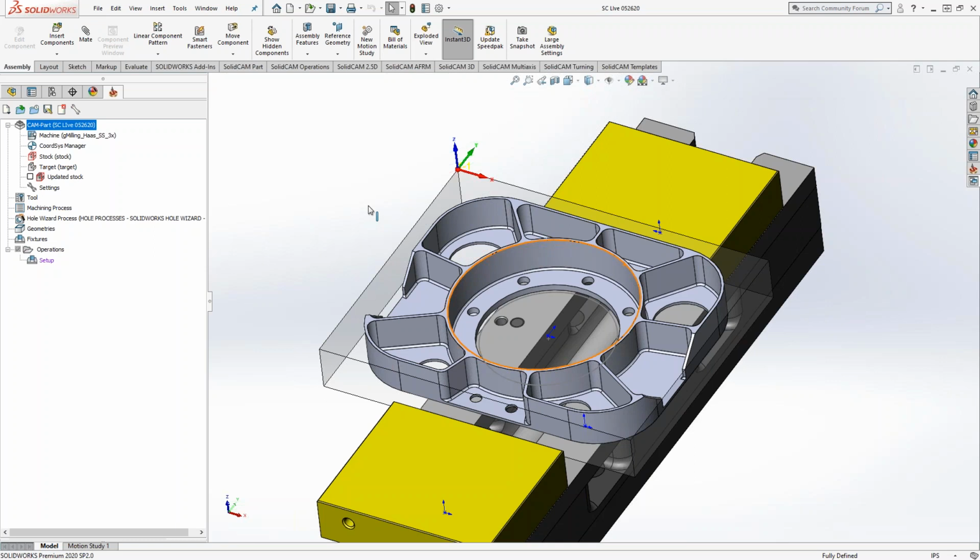And then in your 3D machining, you can put a floor offset. It'll leave the amount of material you're looking for on the top there anyway for that final finishing with a profile or a pocket or whatever. But the irregular shape of this part makes me think I want to do 3D machining. There's a couple of pockets there. I can choose them individually in, let's say, a 2D machining with the pocket recognition. But there's some tapers as well. Maybe there's an outside edge there. And if I have access to 3D machining, it will be the first thing I do. It's the most powerful toolpath. It takes care of everything. I would just do that.